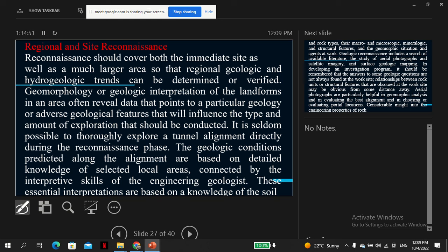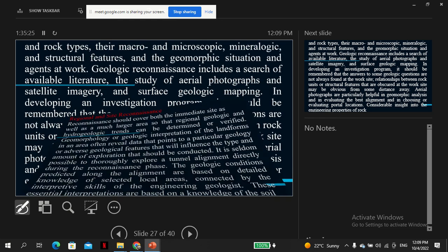Along where you expect the alignment, you can only dig limited pits to see, because the only thing you can be sure of is the observed place, where you have dug the observation pit. From one observation pit to the next, you can only interpolate what might be in between, based, of course, on the data you've observed. But that also requires a skill.